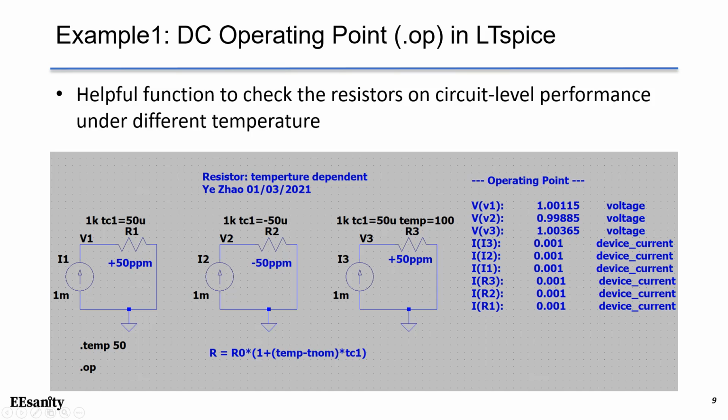So now let's go to LTspice. This is the first example to show you the temperature-dependent resistance. This is a simulation in DC operating point. Temperature-dependent resistance is very helpful to check the resistor's circuit-level performance under different temperatures.